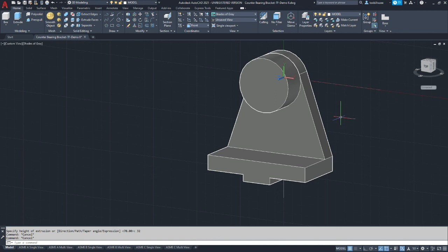Now we need to put a hole through this. So we're going to do a similar process where we pick up on the center of the existing boss, and that gives us the center, and we're going to switch the diameter for our units, and it is a 38.1 millimeter to 37.9 millimeter ream.